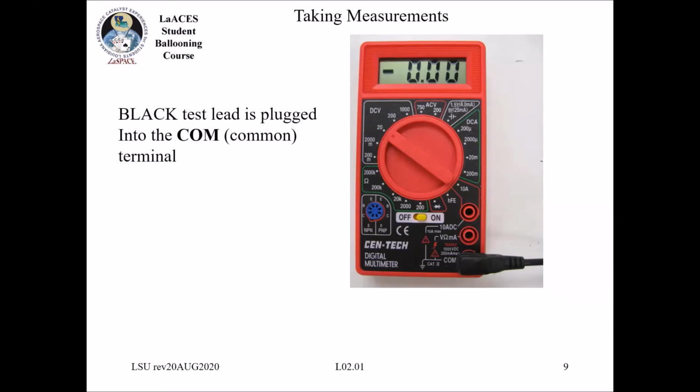If you were to look at an AC wall socket, that is not the case. Make sure you distinguish: there, black is the hot wire. So when we're talking about circuits in this class and you see a black wire, oftentimes that is ground. If you are choosing wires to connect your circuit, it's always great to use black for ground. That way if somebody's looking at it, they say, oh, that is the ground wire.